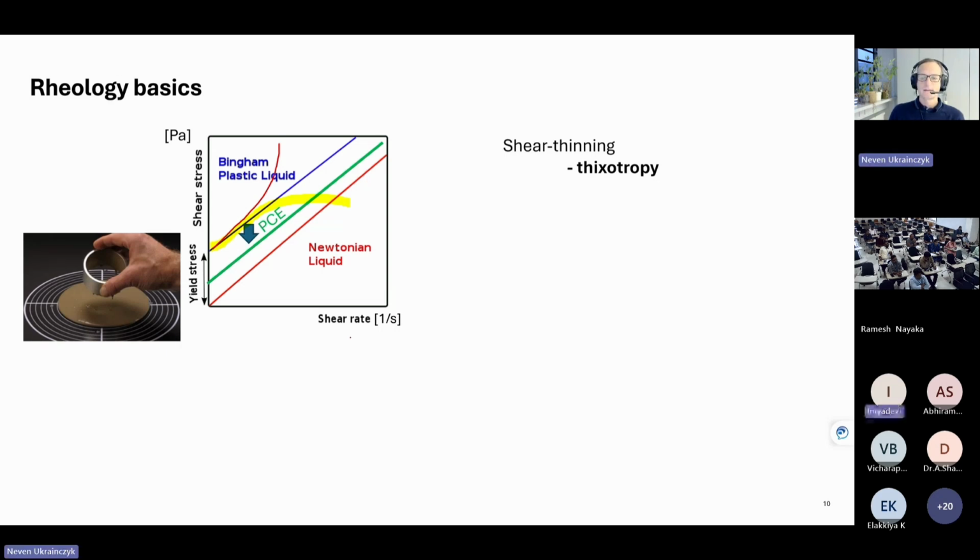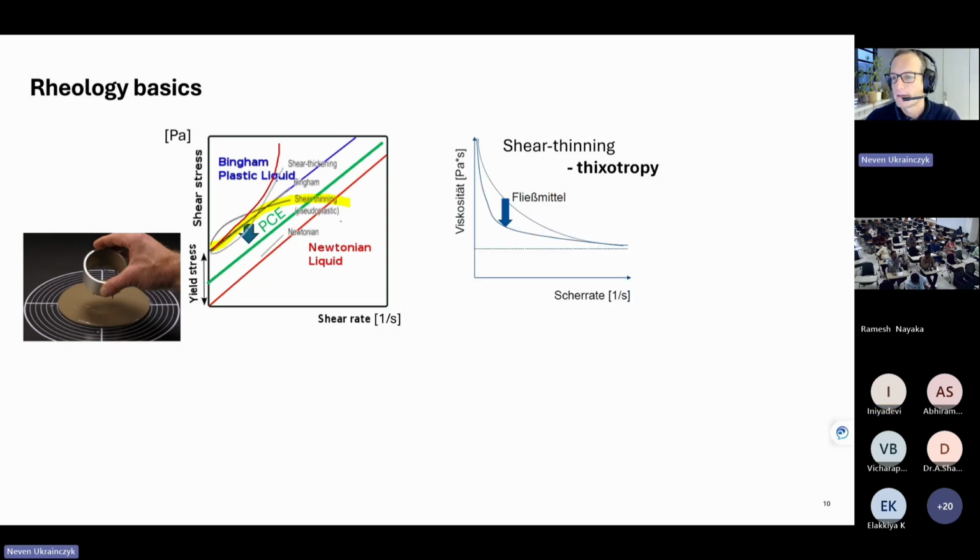That means that when you want it to flow and put in more energy, it actually stops flowing. But this is the example of normal concrete. Of course, in self-compacting or other flowable concretes, you don't have this shear thickening so much. Or you can have shear thinning at the beginning and then later shear thickening, different combinations. That depends on the concrete type.